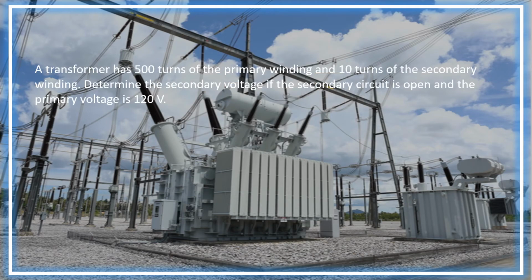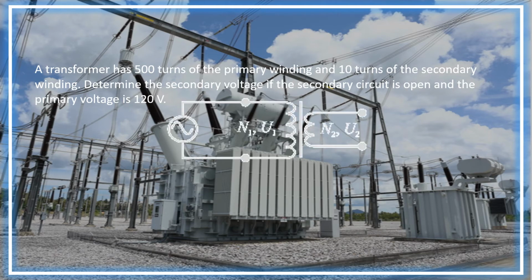For example, a transformer has 500 turns of the primary winding and 10 turns of the secondary winding. Determine the secondary voltage if the secondary circuit is open and the primary voltage is 120 volts. To solve this task, we use the fact that the ratio of the voltage on the secondary and on the primary coil is the same as the ratio of the number of turns of both coils. So we evaluate the unknown secondary voltage. Then we substitute the given values and we get 2.4 volts in the secondary voltage.